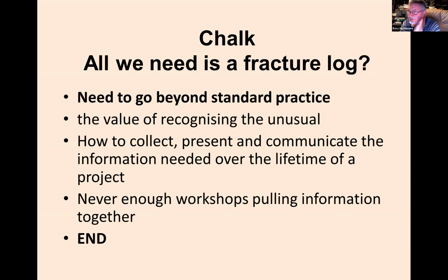But as you saw from some of the core I was showing you from 90 meters down, for example, in the Holywell chalk, the drill bit has broken it all up, but you can still see the natural fractures and natural fracture staining on there. And the surface and the two sides to the fracture fit together perfectly. And so I suspect the drill bit has actually caused it to break up. But that can happen at all depths. And the fractures can be closed at all depths or open at all depths. So it's not a 100% guarantee in terms of applying a grade.